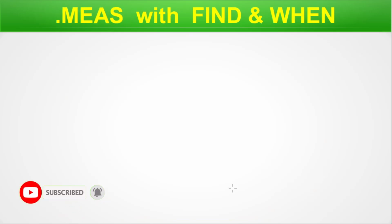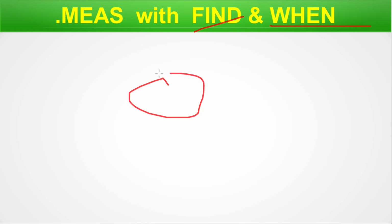Dot measure with find and when. Now we are seeking the time when things are happening. Until the last slide, mostly we were talking about how much time it is taking, and now we will be focused on when it is happening. That means find when this is happening. So that means we have some voltage thing happening at some point, and we will drop a marker in the x-axis, and we will find when this is happening.